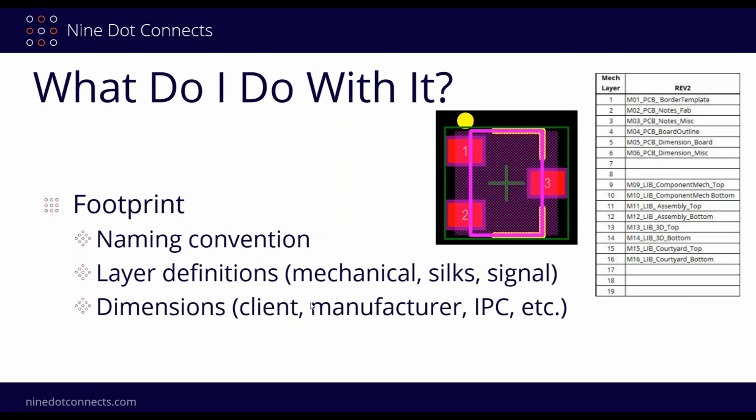What dimensions are you going to use? Are you going to use the IPC dimensions? You're going to use the manufacturer's dimensions? And in some cases for the client, I've seen this now twice, where they are doing special things with their components. One customer is doing encapsulation because it has to be ruggedized. And as a result of that, they have found the manufacturer's recommendation will not work for them. And so they've done their experiments and they have said, no, we've got to build them in this particular fashion.